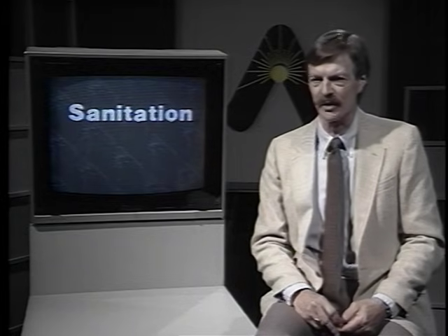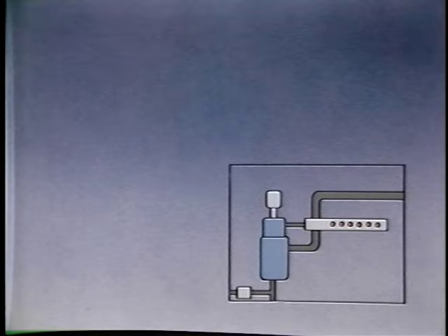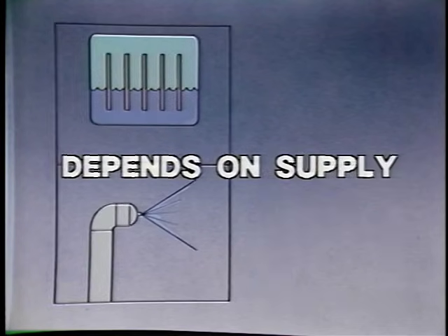Sanitation is a major consideration. Of the four methods, only steam provides a sterile humidification medium if the waterside care and the installation are proper. Evaporative element and water spray methods distribute any waterborne bacteria in the supply water throughout the humidified environment. Additionally, wherever water precipitates out of the airstream and collects, there is a potential for algae and bacterial growth.